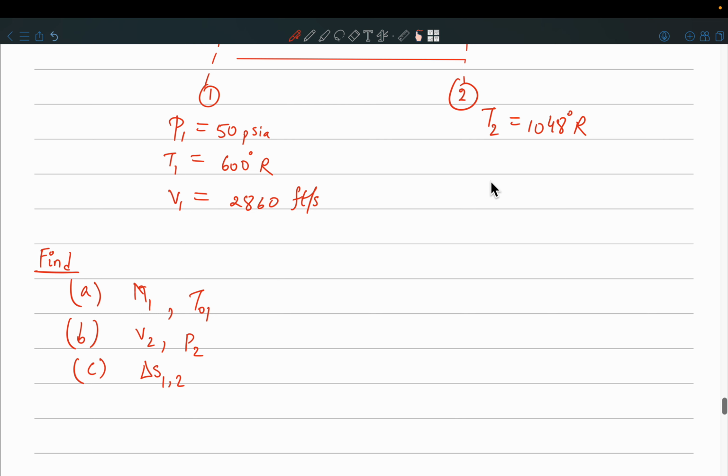I can give you this value. So you'll apply this formula, a equals square root of gamma R T. You can take it as 32.2 into 48.2. There's a conversion factor which will come. So this R into gc is what I've given you. So maybe instead of discussing the exact values, you can tell me how you will proceed.